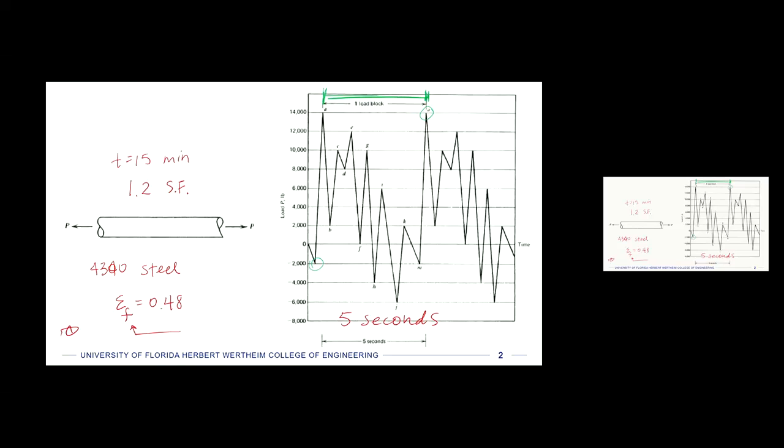We're not going to do the whole rain flow counting, but let's think about what's involved in this problem. The first is a very short lifetime, so low cycle fatigue. So we're going to use the idea that we can partition the strain and see, based on a strain life approach, what we would expect. And since we have this loading spectrum, we're going to use some sort of cumulative damage. We also have a non-zero mean stress.